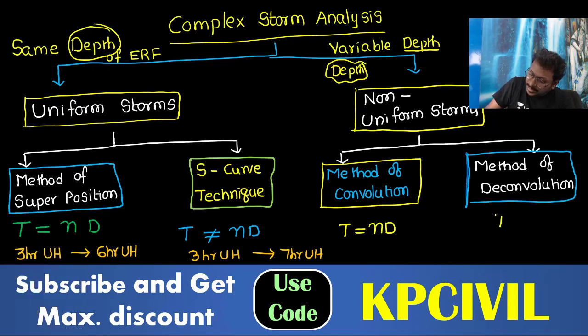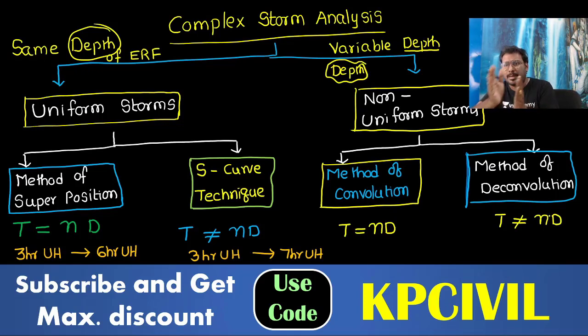Here T is not equal to ND; you can't divide a total storm into n equal number of D-hour storms. That is analyzed by the method of deconvolution or S-curve technique. If depth is the same, S-curve technique; if depth is variable, method of deconvolution. One by one, I will explain each and every method. Don't worry, my dear students.